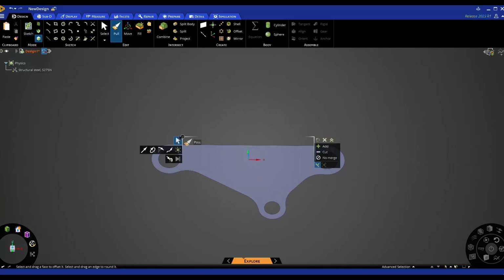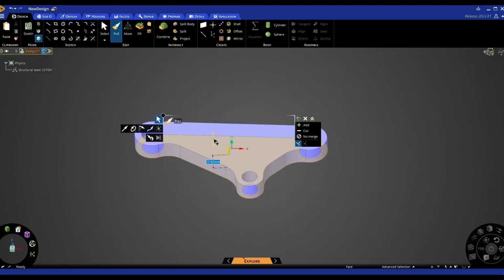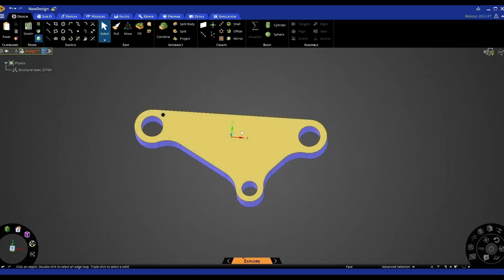and you can see that now my closed curves have created a surface. So the pull tool will allow me to extrude this part up or down. And remember, these same tools can be used modifying other models. So if you are bringing in your models from any other CAD system, we can use exactly the same tools here to make changes and things to your models. So all I've done is use my pull tool just to extrude this face up.